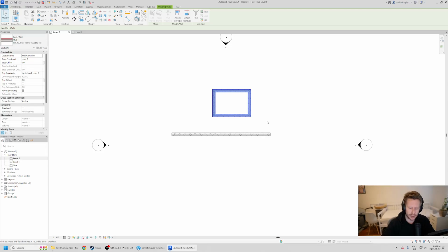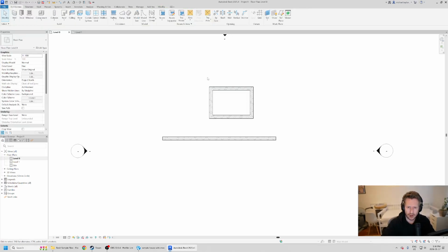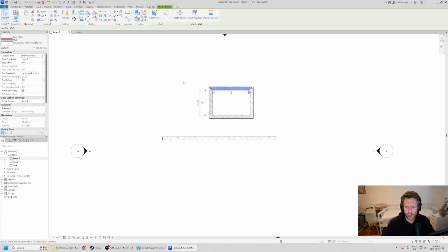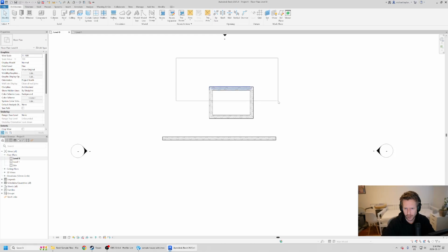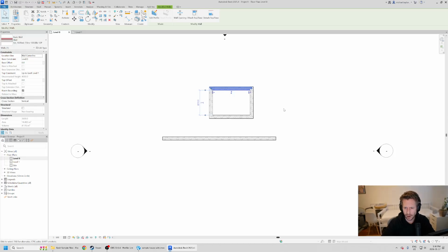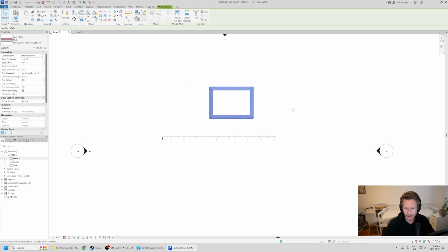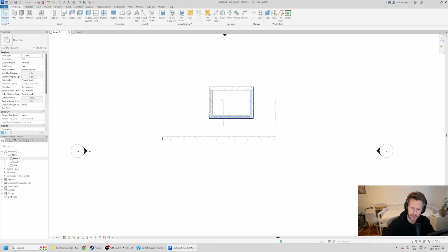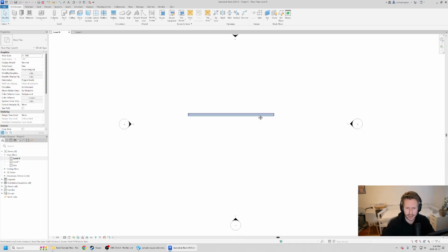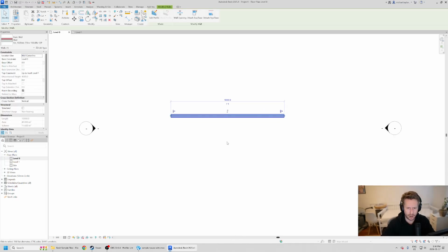If I want to delete something, in AutoCAD, if you remember, if you select something from top left to bottom right, it's only going to capture the item within the window, right? So I click, hold, drag across, and now I've got one wall. If I did it from bottom right to top left, anything that intersects that box becomes selected. Go ahead and hit that delete key. And now I've got my wonderful wall, just hanging out here.